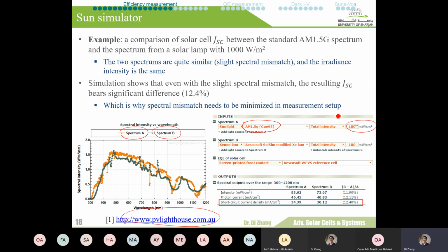In papers, sometimes instead of watt per square meter, they will be using the other unit, which is milliwatt per centimeter square. These two units are both very common, and you can find both versions in papers very easily. But at the end of the day, if you do the conversion, 1 milliwatt per centimeter square equals 10 watt per square meter. So 100 milliwatt per centimeter square here equals precisely 1,000 watt per square meter. So this is exactly the STC rating.